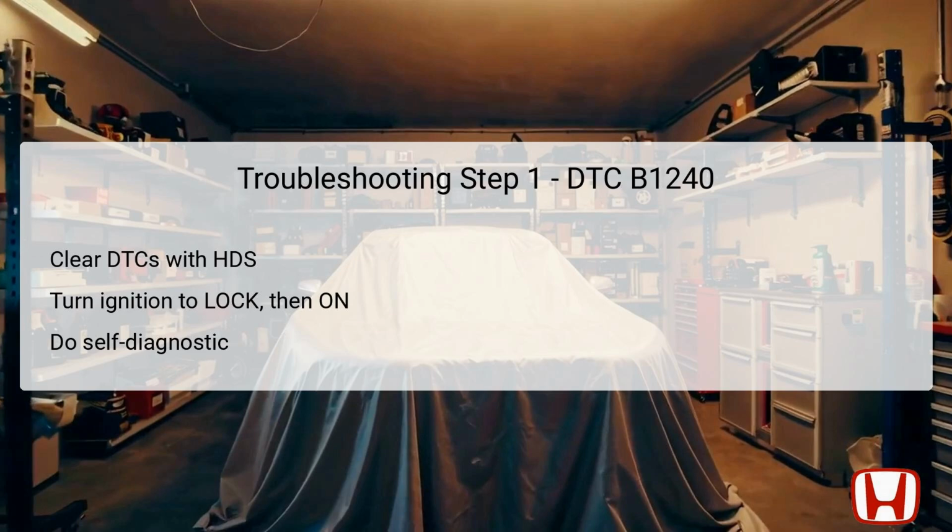In the first troubleshooting step, the goal is to verify the presence of DTC B1240. To begin, clear any existing diagnostic trouble codes, DTCs, using the Honda Diagnostics System, HDS. This allows the system to reset and helps determine if the issue is persistent or an intermittent failure. After clearing the codes, turn the ignition switch to the lock position and then to the on position. This step prepares the system for a thorough self-diagnostic check.